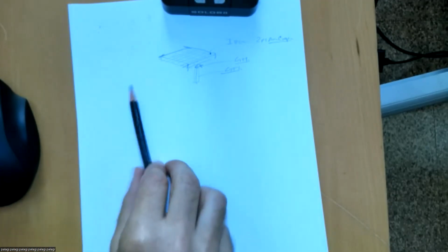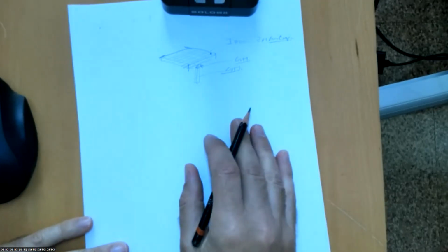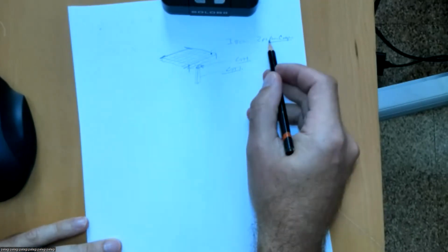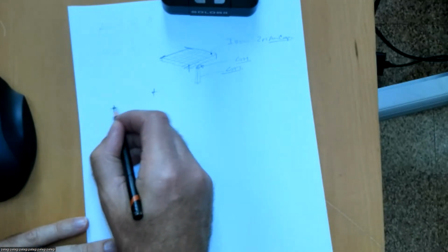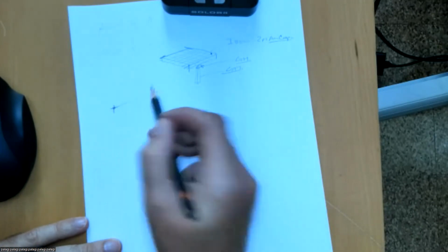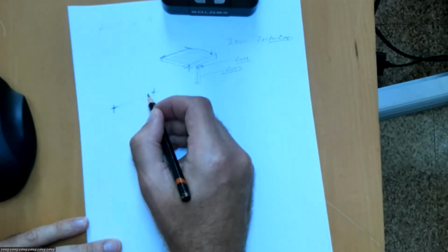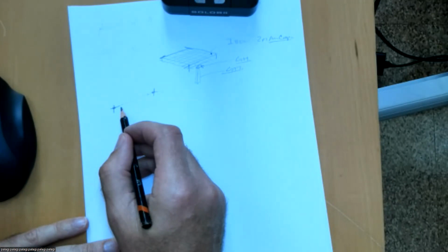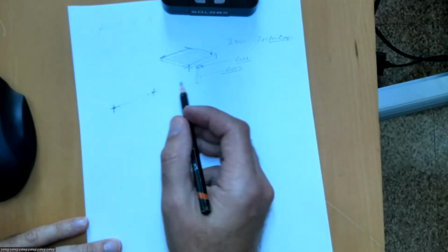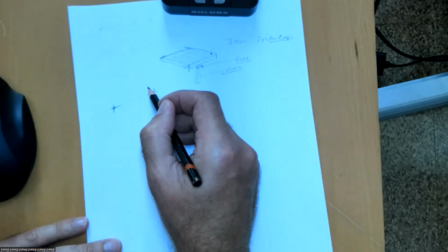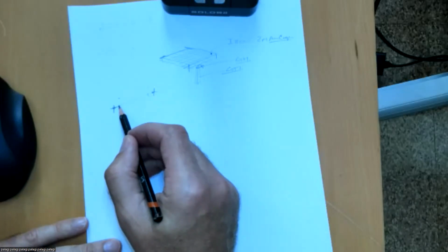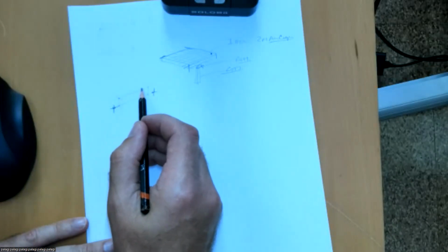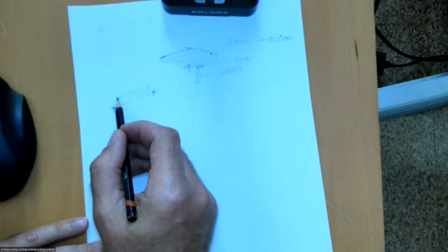Let's see. So when I first do this, I want to draw, again, I kind of sketch stuff out before I've done this. So with the beam, we've done a box beam in the past where we had two adaptive points. We would make a line between them. Remember, we nested points on that line and we set a value for its offset, right? We then hosted a point on top of that at a height and a point on top of that at a height, right? That let us make a reference line around. And when we made the object, we went equal to both sides, right? That's how we did that one.